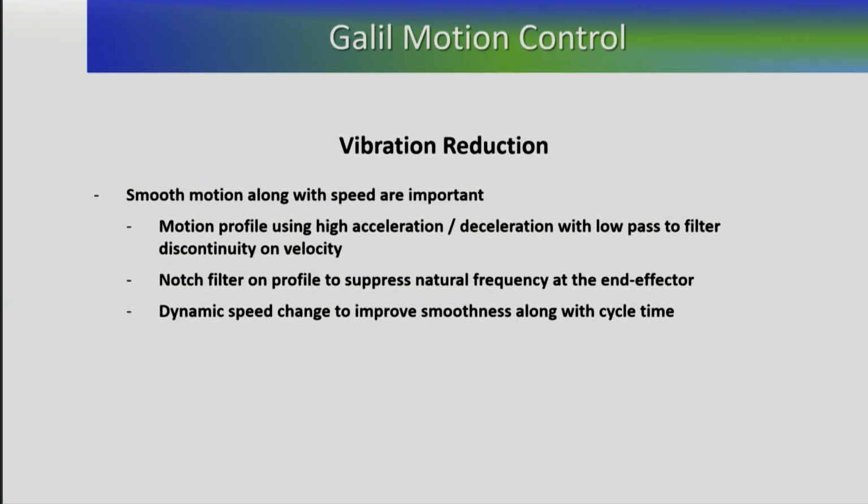Now, once we've gone through and identified the basic components, we go through and optimize it. When you're running this, you start seeing a vibration. So the robot goes through and performs the move, whether it's moving horizontally or extending out. And when you start seeing that vibration, one of the first things is to make sure that you eliminate the vibration.